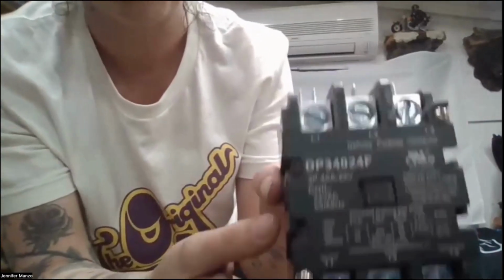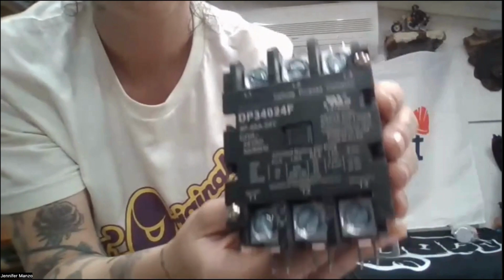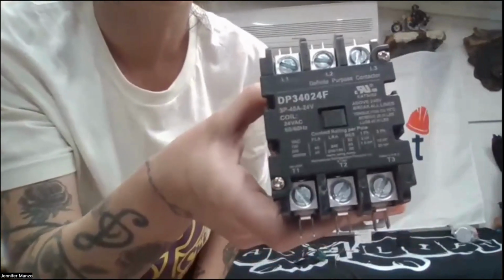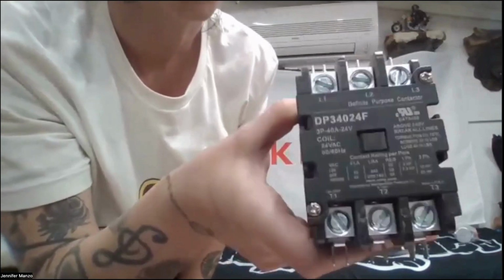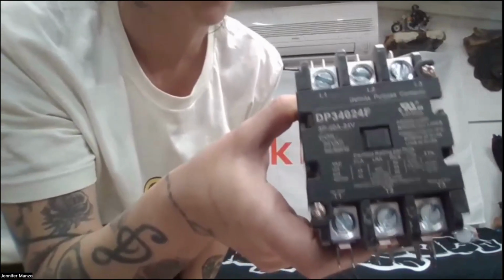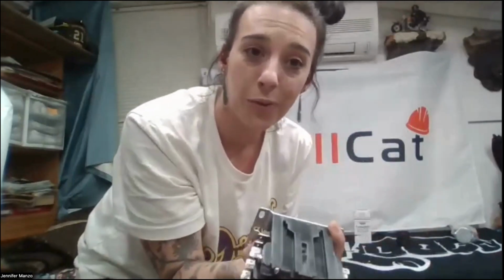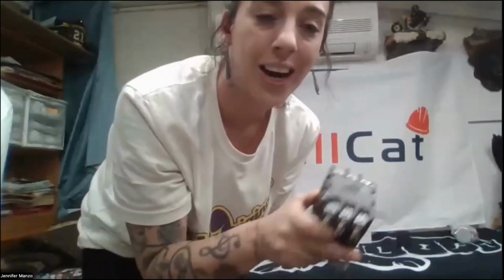They're super self-explanatory. The best way to wire a contactor, and I don't care how awesome of an HVAC tech you are, the best way to wire a contactor is wire for wire. You pull it off the old one, you put it on the new one, and then you move on. What happens a lot is that people want to unwire the old contactor and then they want to wire the new one. When they do that, they forget where stuff goes and they end up cooking stuff. So wire for wire, I don't care if you've been in the field for 50 years, wire for wire on a contactor.